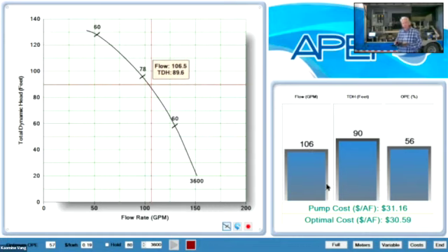Okay? So that's kind of your basic showing the soft start. So that's the first thing I wanted to demonstrate. You can buy a soft starter without the VFD that can do that for a little less money if all you need is a soft start. Let's say you have a 400 horsepower, big giant pump, and the power company goes, hey, our transformer won't handle it. You have to have a soft start, wind it up slowly.